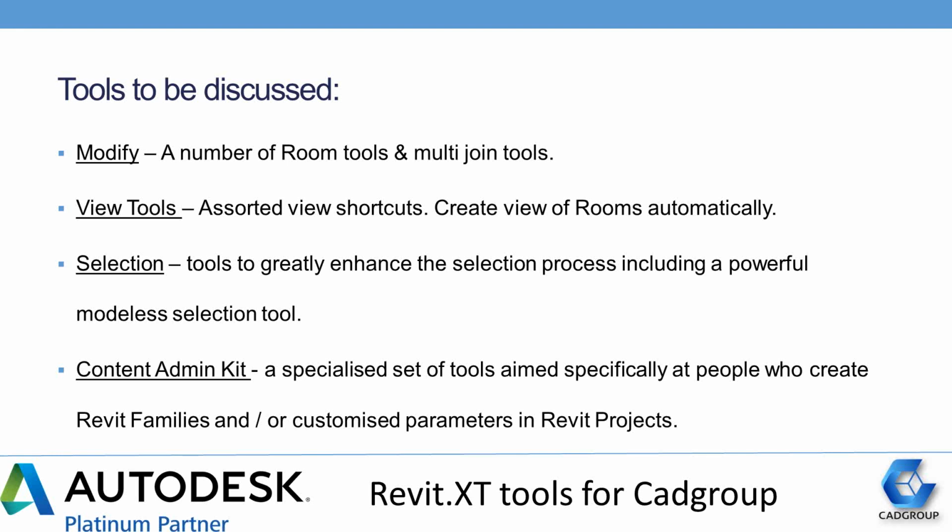The selection tools are an enhancement of the selection tools in Revit. For example, there's a modular selection tool that allows me to go through and select individual elements based on a whole heap of criteria. And as I make those selections, my model updates dynamically, so I can actually see the net result of my selections or filtering as I'm making them. There's also a really good filtering tool, which, when I've made a whole selection, as you know in Revit, allows me to filter out walls, floors, and so forth.